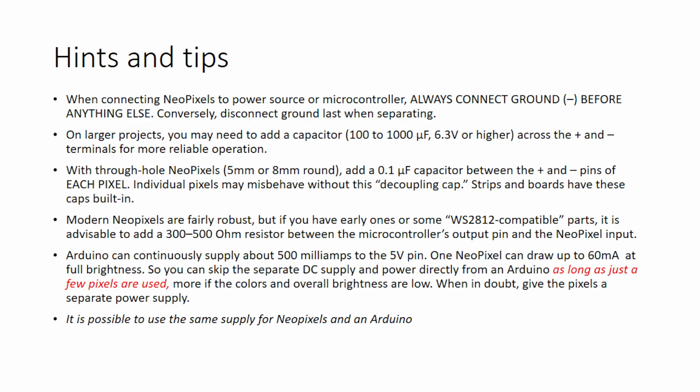You sometimes need a big capacitor, but that's becoming less and less of a problem. And as you see, nearly all the boards that you buy from China have got the capacitor already on them, and they've got the series resistor already on them. So that takes away the thing about the decoupling.